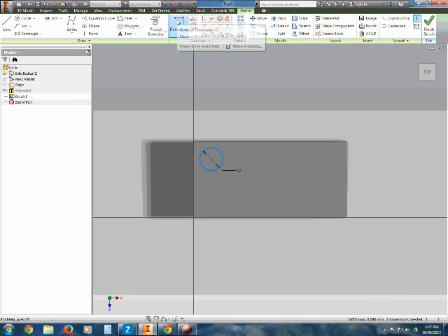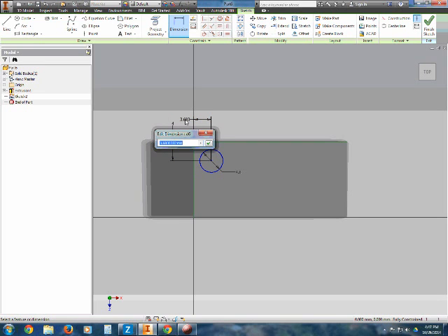So we're going to grab the dimension tool and dimension the distance from this line to this center point. Make sure you click those points or those locations, and that distance is going to be 4. So I clicked those 2 points and then click to place a dimension. You need to click on it again to type in the new dimension. And then the distance from here to here is also 4. And you'll notice by putting those dimensions on, my sketch is now fully constrained.